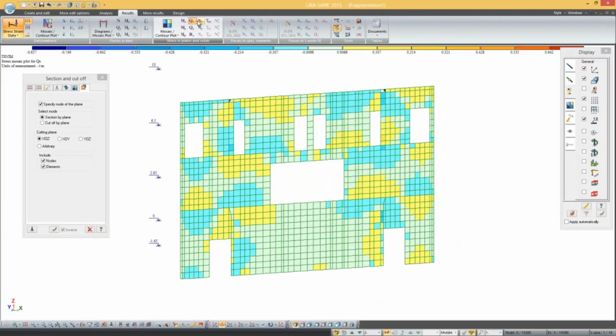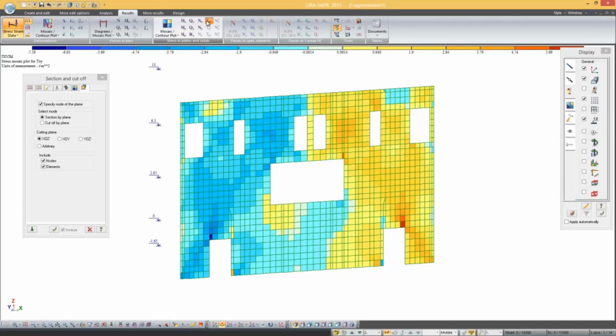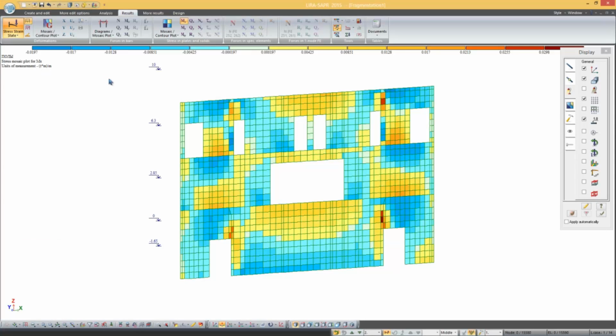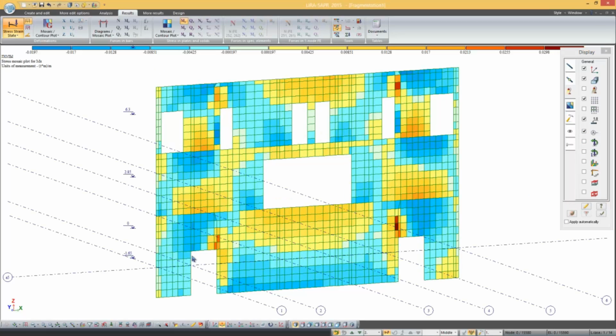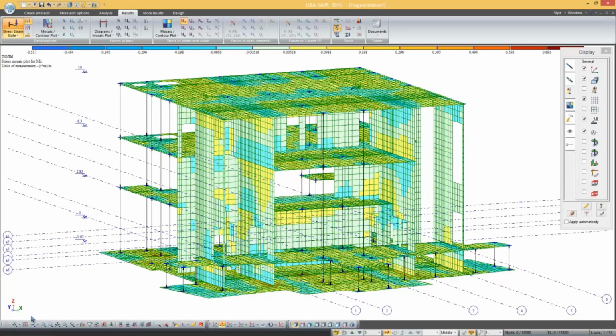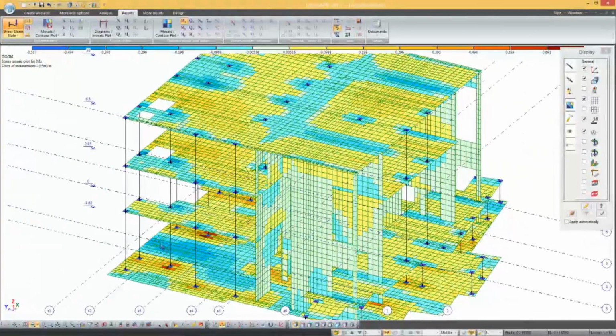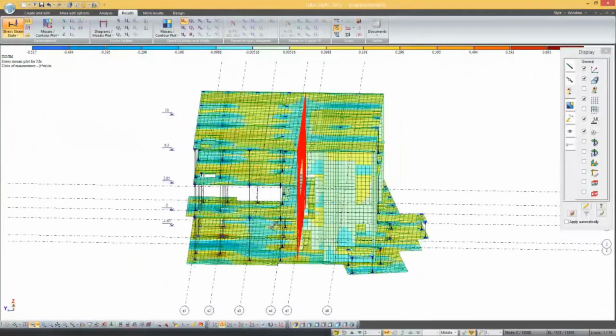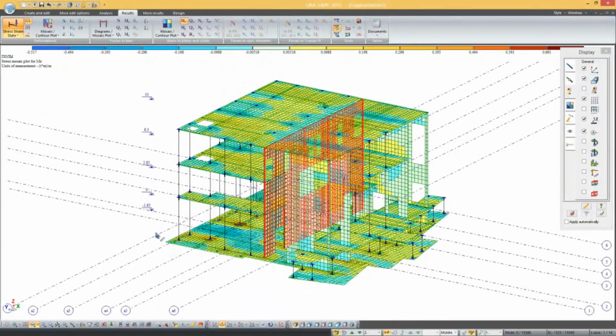Now I will show you another easier way to perform the fragmentation of vertical elements. As you have already guessed, we will use the construction lines. In the flexible drawings, I will select the bottom construction lines. Using the tool Element Select, I click on the construction line marker, for example of the previously selected diaphragm, and all the elements that fall and lie on the construction line will be immediately selected.